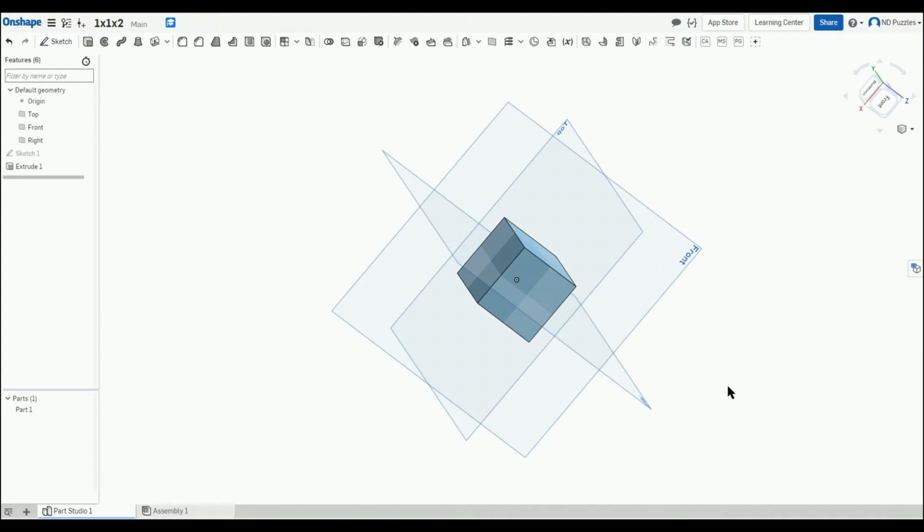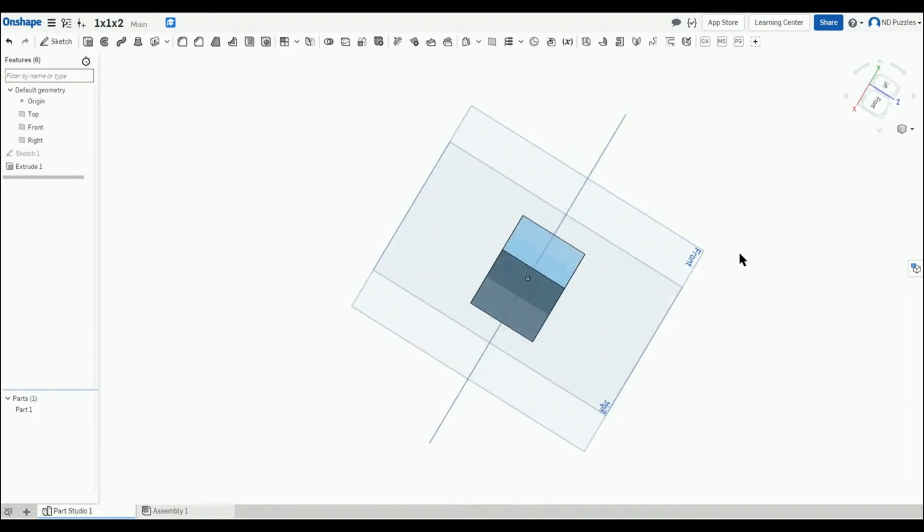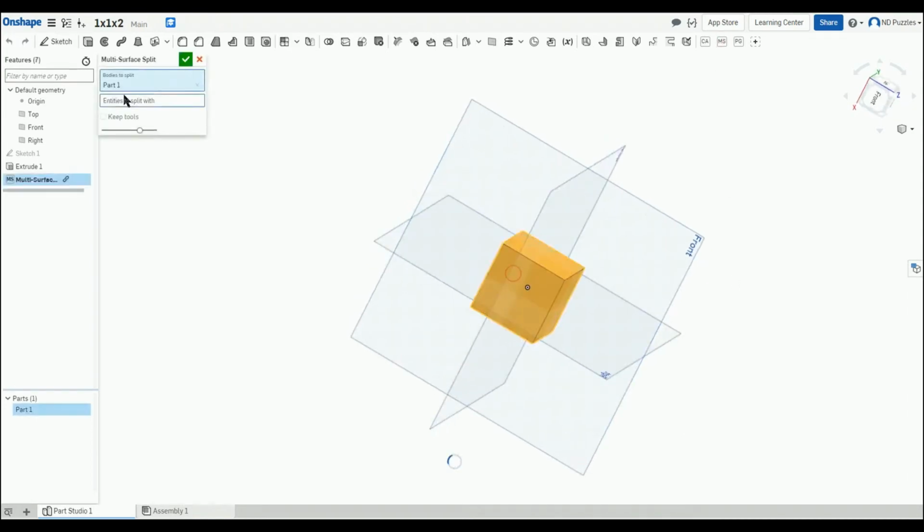Once you click on the icon, a new menu opens and asks for input. First you have to choose the face or sketch you want to extrude. So click on your mighty rectangle now. If you now use the mouse wheel to move the three-dimensional room, you will notice that it has actually created a solid block out of our sketch.